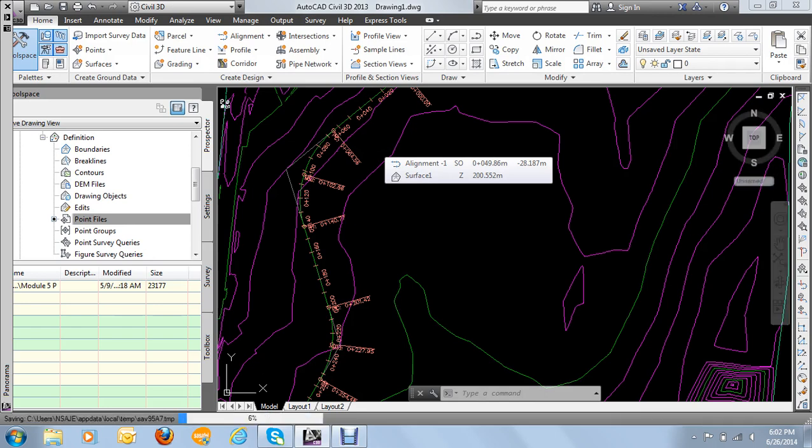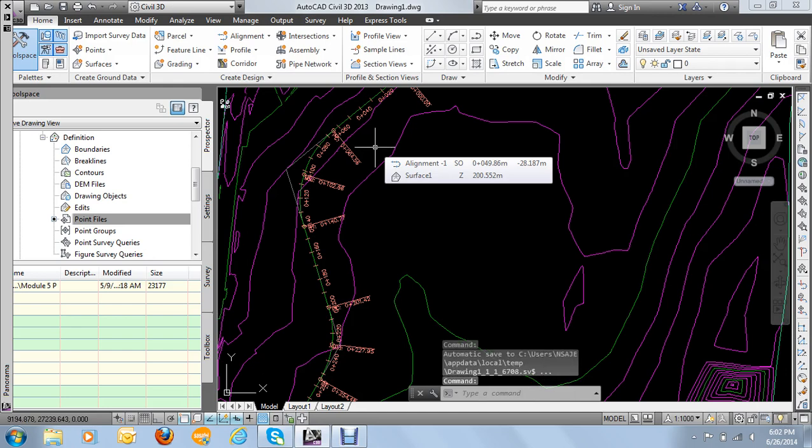Then you come up with the elevation of the respective points, and you'll also know the station or chainage of each point. So you're going to use the data from the existing profile to redesign it. Or the other way, you're going to redesign the profile by passing through the existing one, if there is no strong evidence that requires you to go back to site.